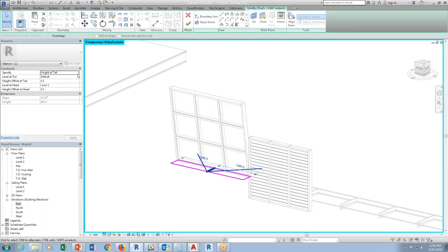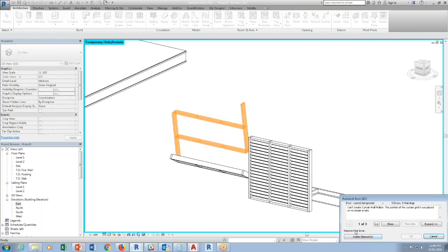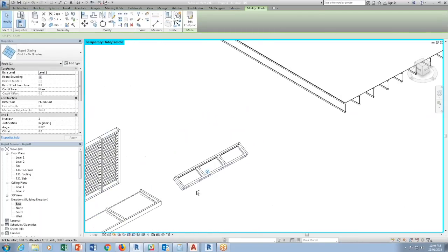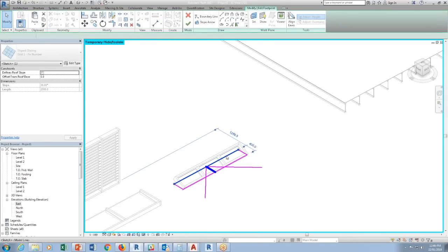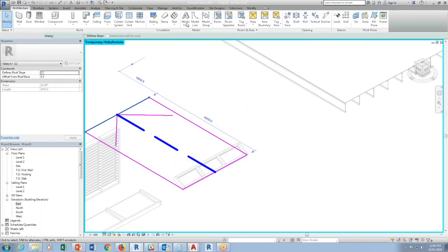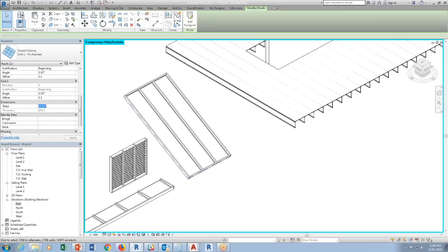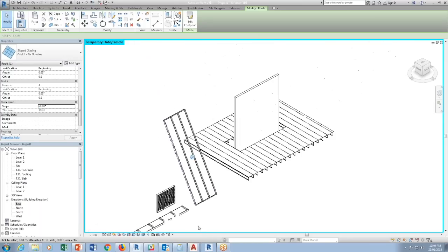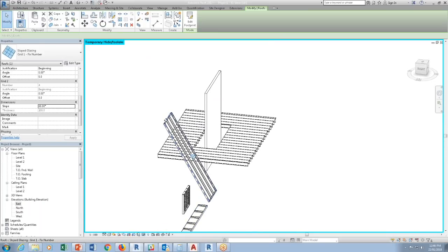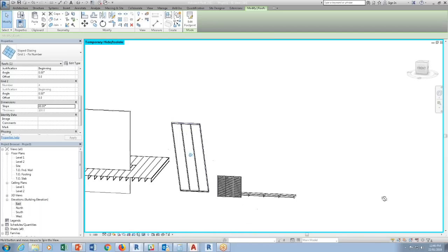Okay, if you want a specific angle, then again, you just go edit. This is where you say, okay, I no longer want that, I want it to be basically go slope. And then this is where you say, okay, I want 30-degree. Okay, it's going to delete that element. That's fine. Okay, there we go. There's your thing, and then you can say, I want it to be as much as I want, and instead of 30-degree, let's make it 60. So here you can change it here. You can say this one I want to be 60-degree. What it does is that it depends on where this is. It will basically just do an offset angle. All right? Any questions so far?